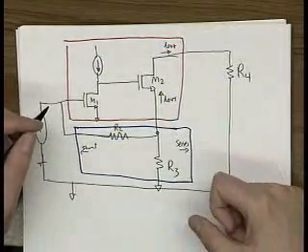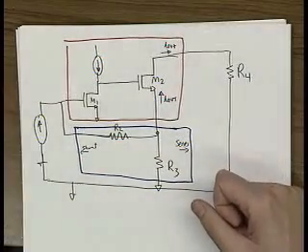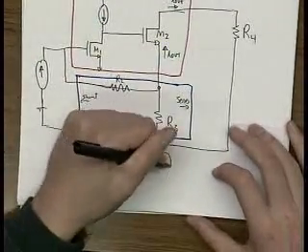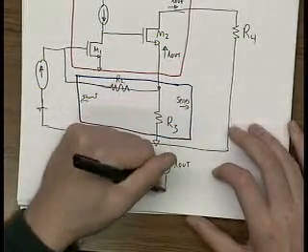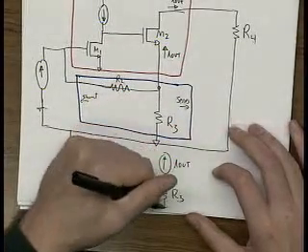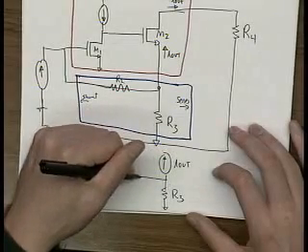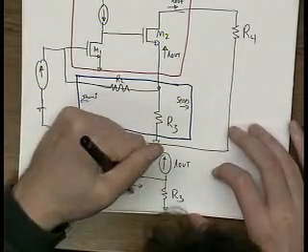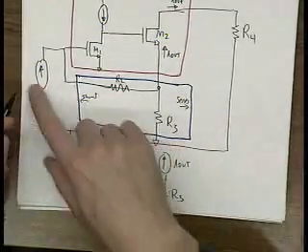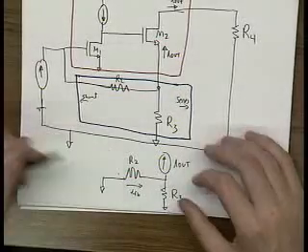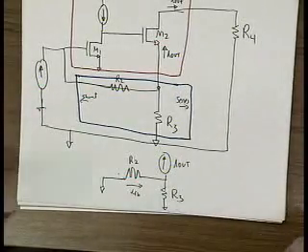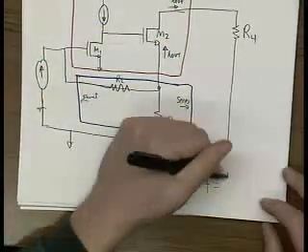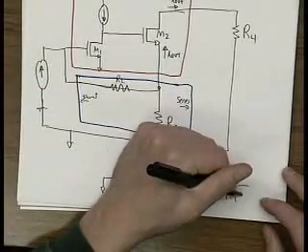How much of it gets fed back? So what we have, our feedback network looks like this. I out, R3, R2. This is I feedback. And because it's a shunt on this side, this looks like a low impedance node. Okay? From there, we can directly calculate that F, it's just a current divider, is equal to R3 over R2 plus R3.